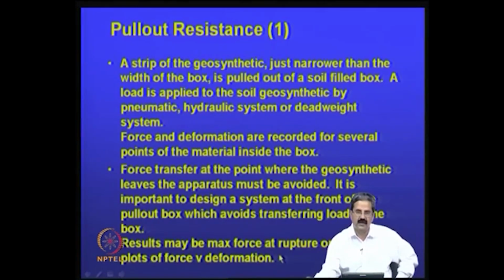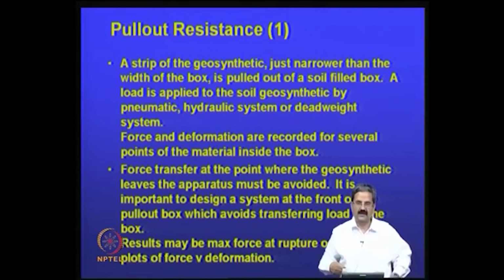There is another test which we have to do, called the pull out test. As I just mentioned, in the concept of reinforced soil, you have friction in the active zone, and the reinforcement has to be held in position at the back side. That is called pull out resistance. That pull out resistance is very important for effective functioning of the geosynthetic material, and the way we do it is that we calculate pull out versus deformation.